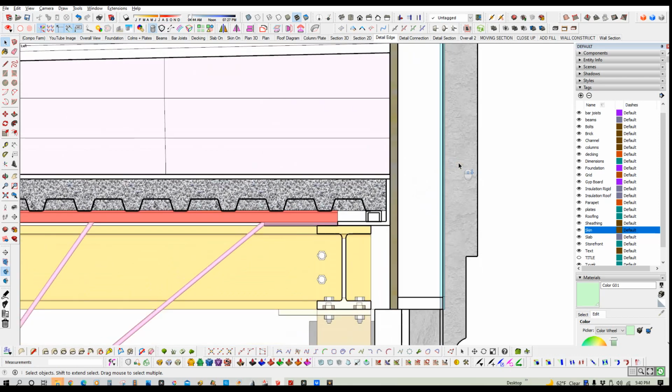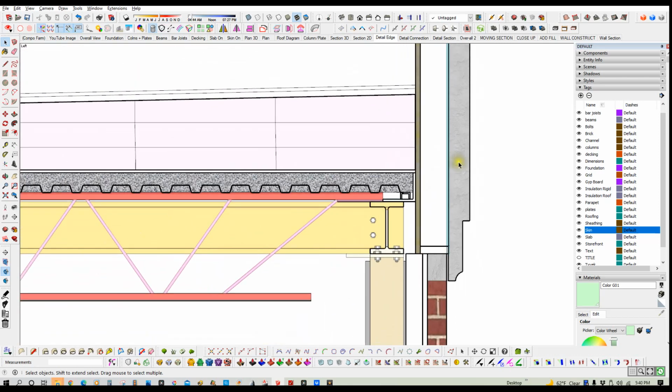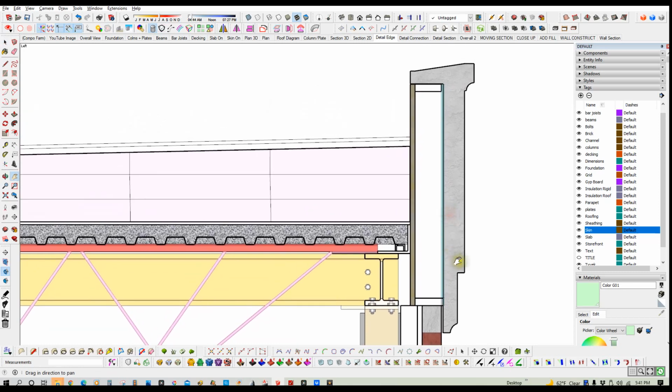The nice baby blue stuff, purple sometimes. The gray is a parapet, probably done in, I don't want to say Dryvit, but a material that I'd call a synthetic stucco, probably formed with expanded polystyrene. So it's lightweight, so it can hang easily on this metal stud wall. That's what this is here.